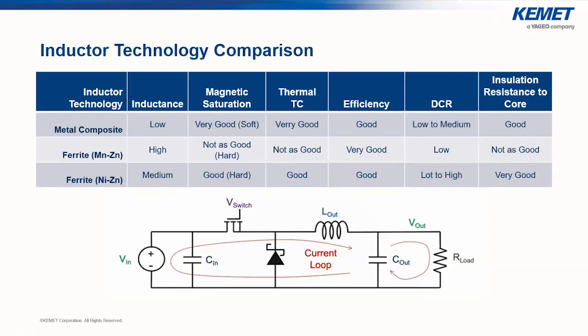For those who might think this is not important because they are at lower temperatures, please consider that a higher temperature rating also makes higher current values possible. So this is not only about your own application. If you have 100 degrees and you don't think you need 180, the 180 version will allow higher self-heating, and therefore you can put higher currents on the inductor. The current flowing through the inductor always heats up the component, and the higher the temperature the component can take, the smaller and cheaper the component you can use. So finally, high temperature means high current.